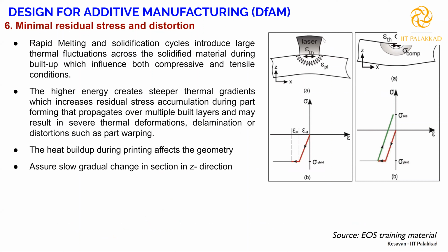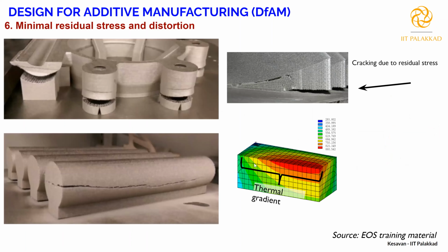The moment you remove the heat, the liquid will try to contract because solidification is taking place. Since you have different density across the melt pool, at different locations you end up with different strain values, right? So the net strain will give you some residual stress. The effect of net strain will not be uniform, so that gives residual stress. This is due to uneven expansion and contraction while heating and solidification. So that's what causes the residual stress in the component. There are many ways to handle it.